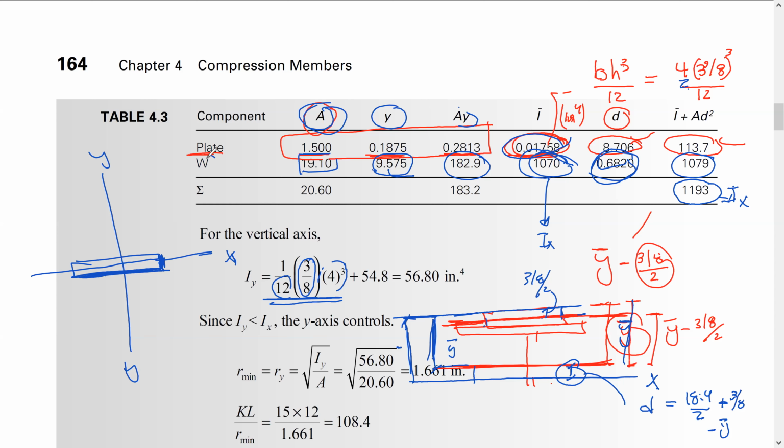For the wide flange from the manual, you will get Iy and this much. And if you look here, we did not use the parallel axis theorem because this shape is symmetrical about the y-axis. So there is no difference, okay? The neutral axis was through the axis of symmetry, so there is no need to do the A d square part. Right now we got the geometrical properties for the built-up section. And you know, for the hot rolled sections, you didn't need to do all these calcs because they are available in the steel manual.